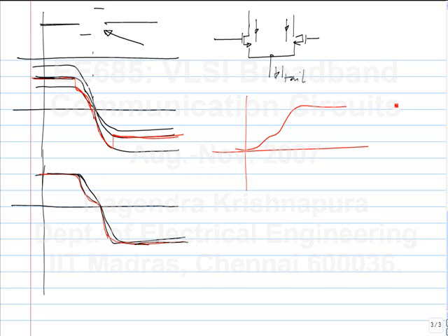We are of course using the non-linearity in a certain way. If you double the input, if you see double the value, that is a measure of linearity. But that test you can't apply. In this case, you are using some non-linear elements to realize a linear transfer function. It's not as though it is continuously linear. You are using in fact a differential pair in a switched fashion. So if you double the input, you don't see anything. So you make a positive transition and a negative transition, and the sum of the two should be 0 if the response was linear.